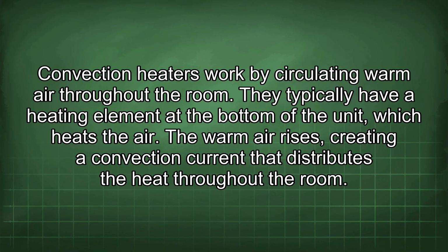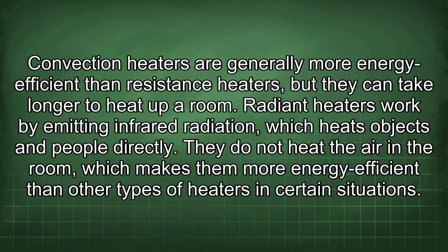They typically have a heating element at the bottom of the unit which heats the air. The warm air rises, creating a convection current that distributes the heat throughout the room. Convection heaters are generally more energy efficient than resistance heaters, but they can take longer to heat up a room.